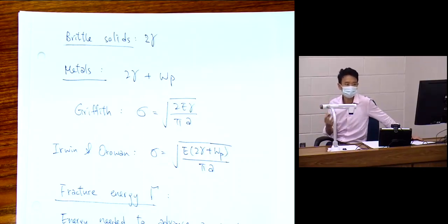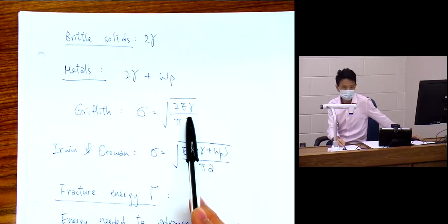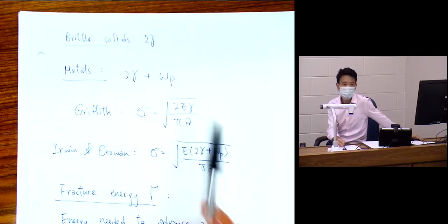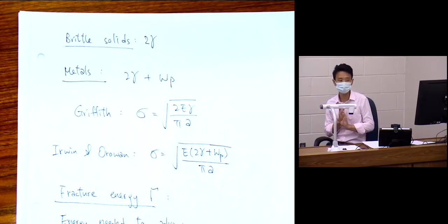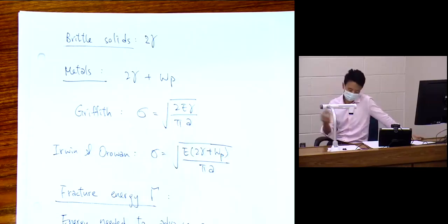And that means that there's more resistance in addition to surface energy, and so then what we need to do is just to modify that surface energy term, right? Because in the Griffith formula, that represents the only parameter that resists fracture from the material. Stress is being applied, crack length is just a geometric dimension of the crack, right?